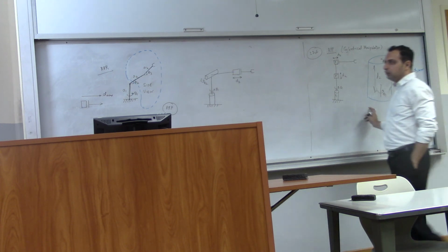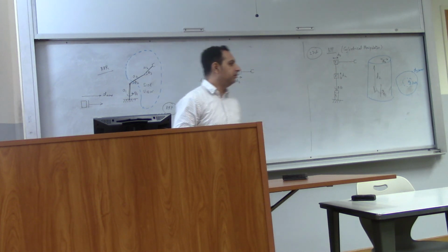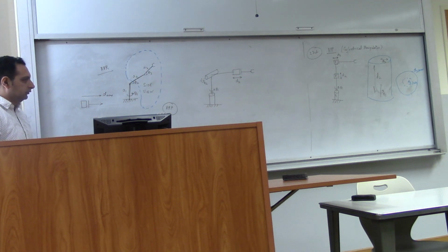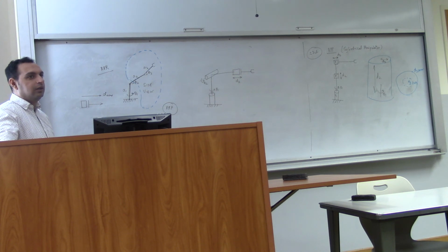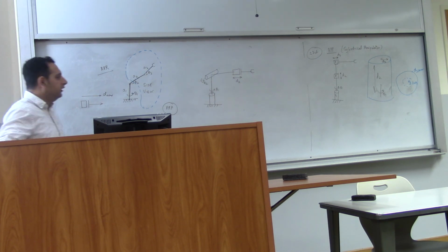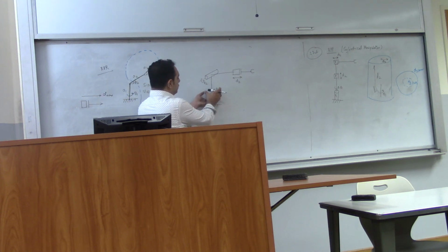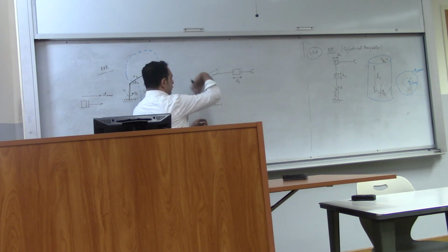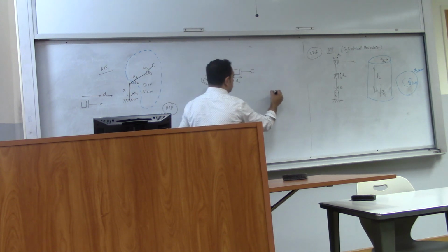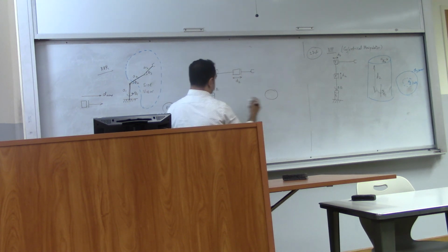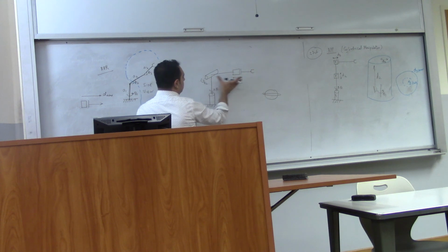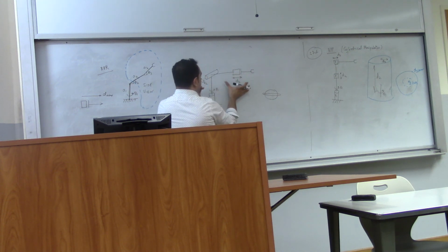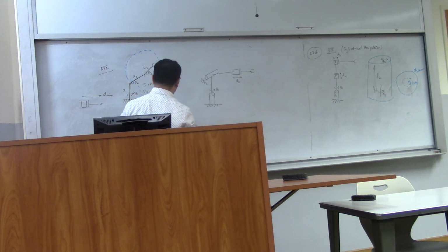Okay, so we're trying to plot the workspace. What will be the workspace of this manipulator? It'll be a sphere, right? So this will generate one motion, which is round, and this is going to turn it over. So this will draw a circle like this. This will generate a circle which is a disc like this. Okay? So the extent of the sphere will depend upon what is D3. So in this case, this RRP is a spherical manipulator.